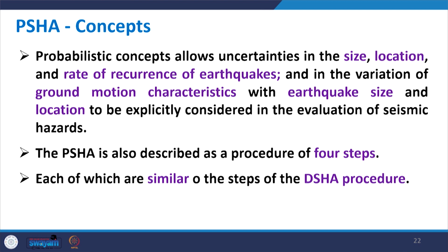The probabilistic concept allows uncertainty in the size, location and rate of recurrence of earthquakes, and in the variation of ground motion characteristics with earthquake size and location, to be explicitly considered in the evaluation of seismic hazards. So this is about the chances, the probability, and that is included here.